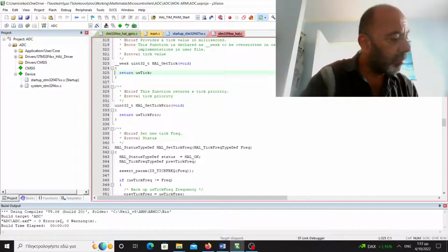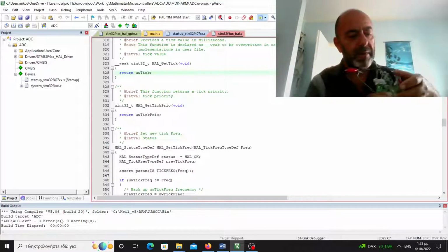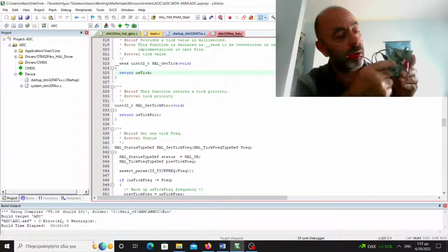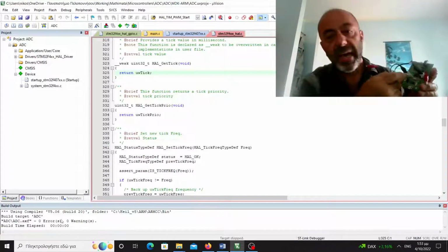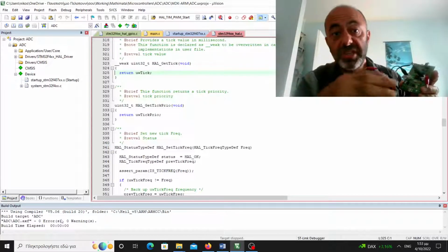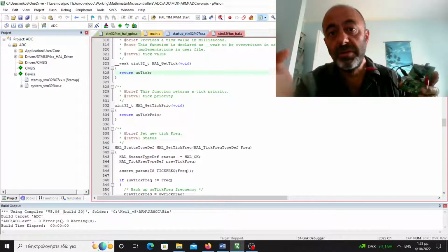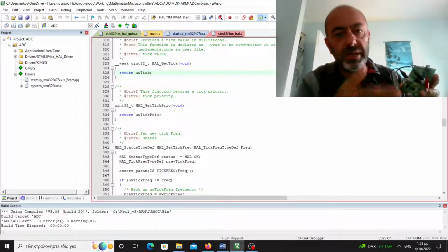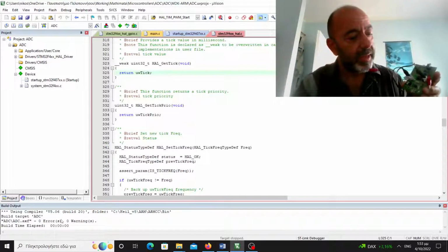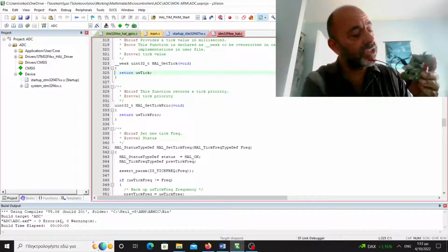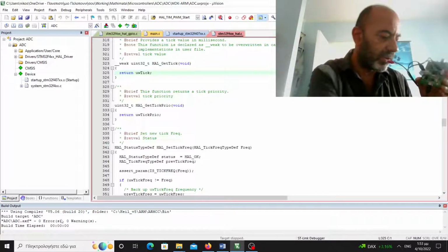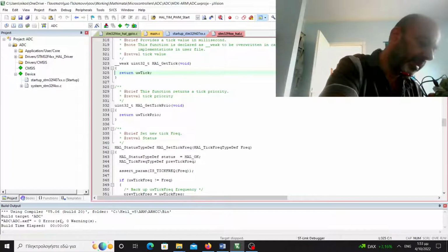So what I will do is to connect my board, but as you see here, what I have done is that I have connected to the PA0, which is on this header, a 3-volt voltage, which is a non-zero voltage, the smallest non-zero voltage that I can get without using additional components, in order to see what will happen here. Let me do a demonstration and then I will explain the code afterwards. So I connected to my USB port.